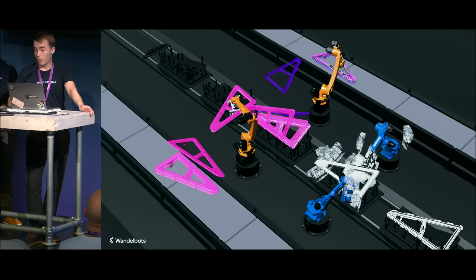Then you get this. If we want to make the placing of the empties easier, we can use ghost teaching, a bit more refined technique. We parent the TCP empties to the end-of-arm tools and workpieces to get a good feel for the positions they will actually end up in when moving. These instances are also a great first step for just rough collision avoidance, just looking at the scene and determining what it might collide and what it might nudge in the process. On top of these practical implications, it also gives us a first chance at roughly animating the interaction. Using constraints in Blender will come in handy at a later stage especially.